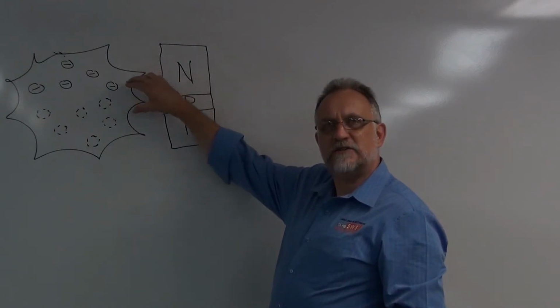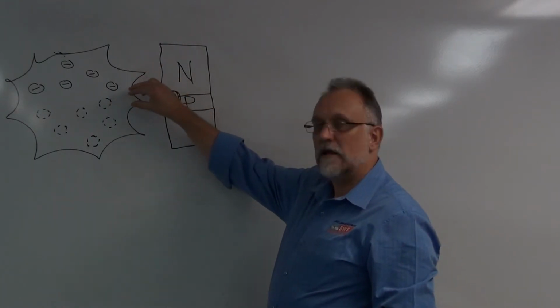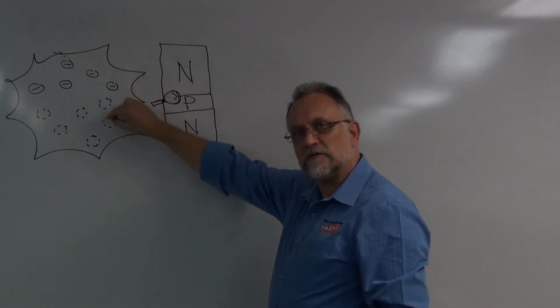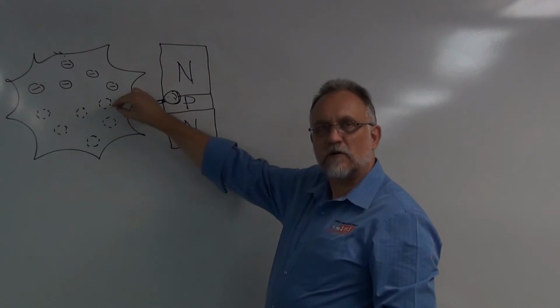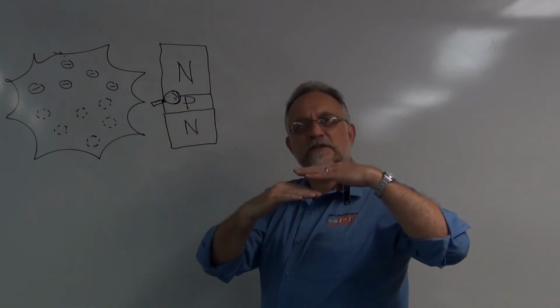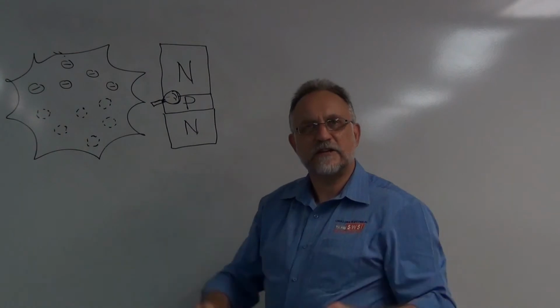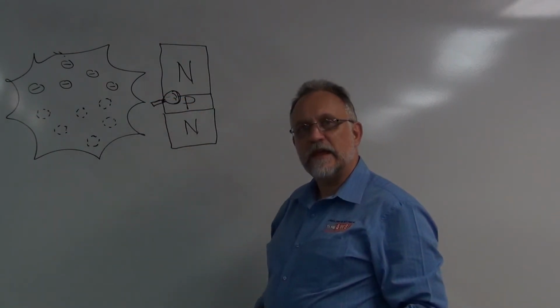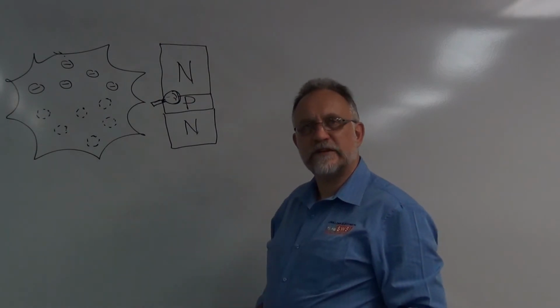Because as you mix the layers together, the spare electrons identify where the holes are and fill those holes just in the area surrounding and across that junction. What we end up with in the middle is a layer which is perfect crystal. Perfect crystal in a semiconductor doesn't conduct. And that means that we end up with a non-conductive layer between the N-type and the P-type material.